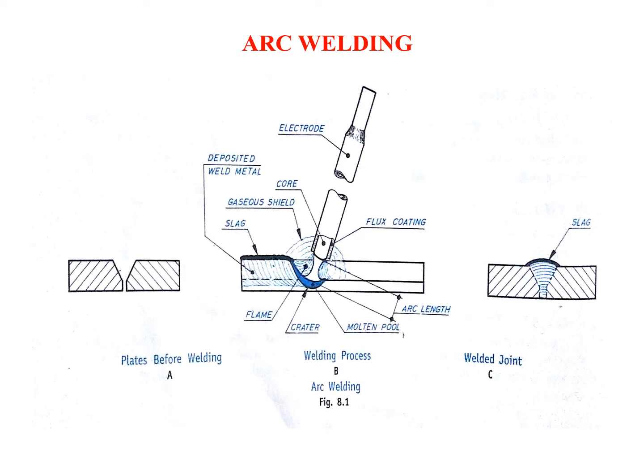Also you should remember the temperature range, because it is asked many times in the exam, what is the temperature of arc welding. At that time you have to write that it is about 5000 to 6000 degrees centigrade. In arc welding, usually the parts to be welded are wired as one pole of the circuit, and the electrode held by the operator forms the other pole. Here you can see, this is the electrode, formed as one pole, and this work is formed as the other pole.